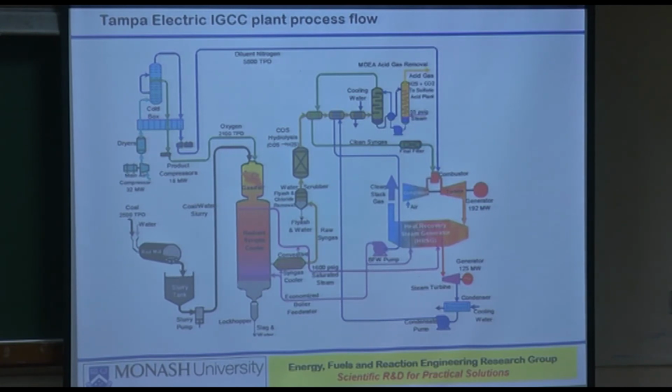The final filter will remove any very fine particles as well as whatever goes with this gas. At the exit, I think they have just shown it so that that's what is attractive for sulfuric acid manufacturing. But then, when I talk in a couple of slides about membrane separation, the fundamentals of it, how we can, from a mix of gases consisting of these pollutants, hydrogen and CO2, use the different types of membranes which are available and who the suppliers of these membranes are, we can take out gases through a series of membranes one after the other.